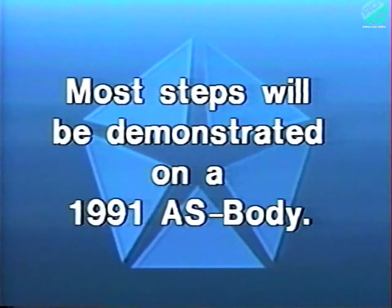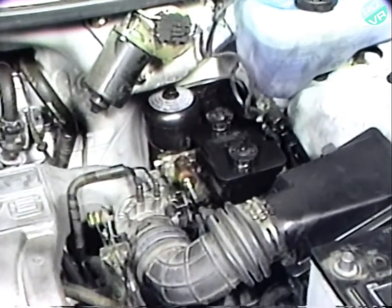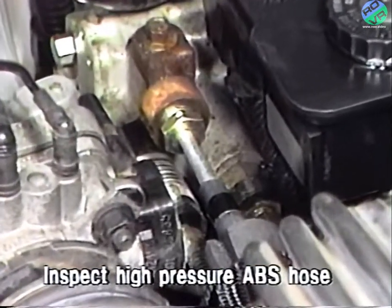Most steps of the following service procedure are similar for all involved vehicles and will be demonstrated on a 1991 AS body vehicle. For Eagle Premier and Dodge Monaco, the high-pressure hose replacement procedure requires several additional steps, which will be shown separately later in this program. To begin the service procedure for all involved vehicles, you must first determine if the vehicle requires the recall service package by inspecting the high-pressure ABS hose that is on the vehicle.